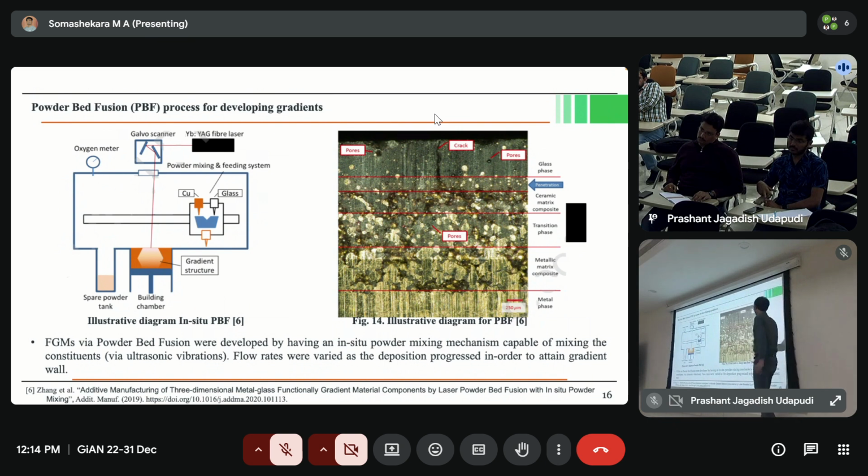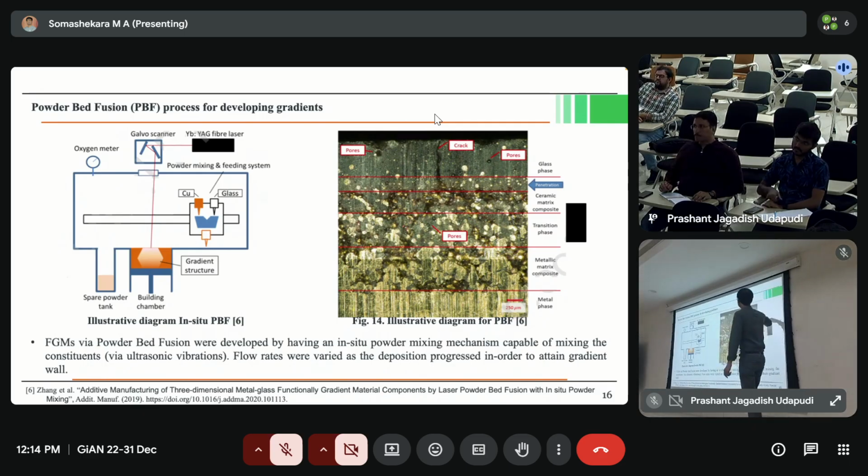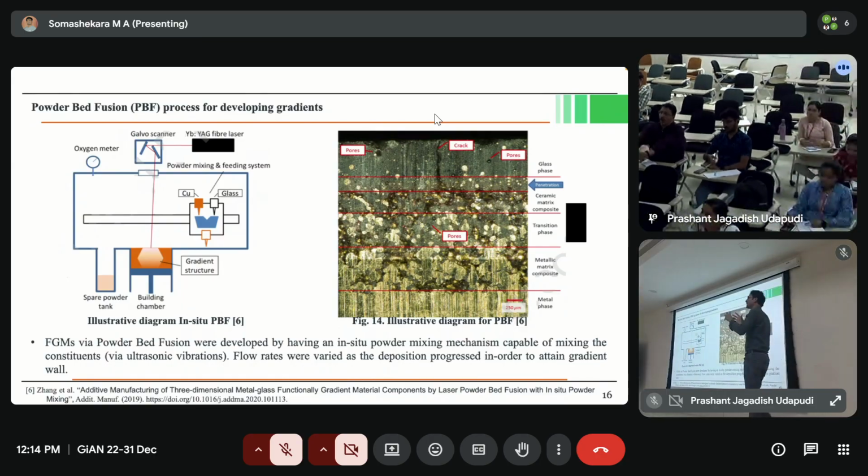You can see how bad the structure formation is here. They don't go well together because their composition is completely different. When the composition is completely different, the melting also varies. For example, the melting temperature for material A may be different compared to material B, right? Now you try to join and mix them together, and then you give the same power.